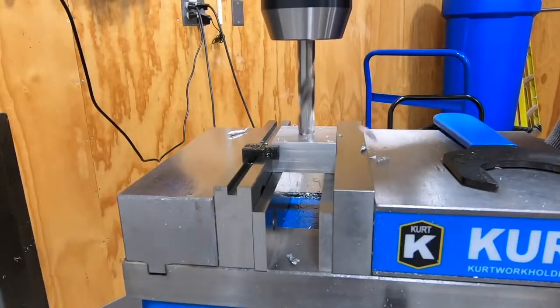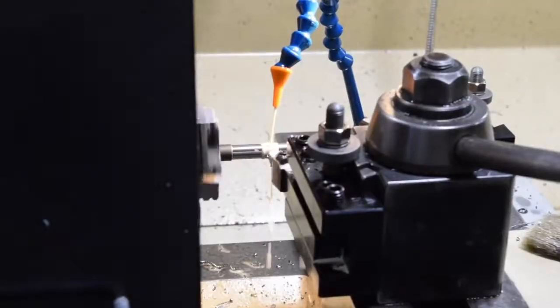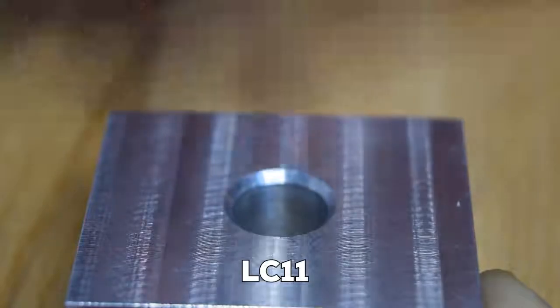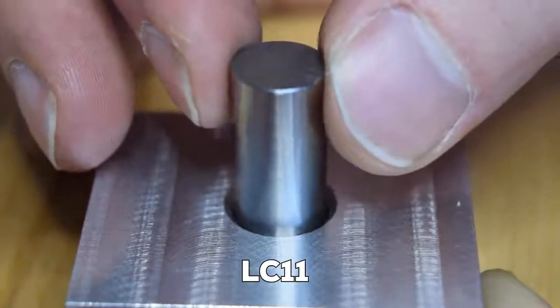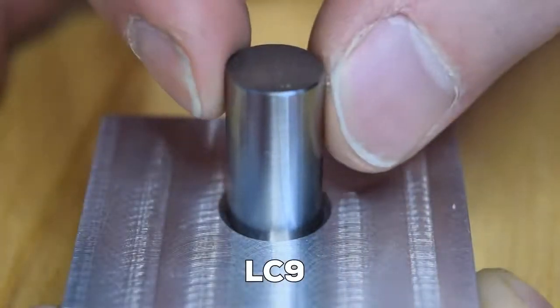These tolerances are extremely loose, so drilling the hole with a regular drill is sufficient. Hitting the shaft tolerance on the lathe is also no problem, and other processes like forming and extrusion will probably hit it as well. This fit is used where you don't need accurate alignment of the mating features. The clearance around a bolt is a good example of this, since you typically don't use a bolt for precision alignment. This is a slightly tighter locational fit, LC9.